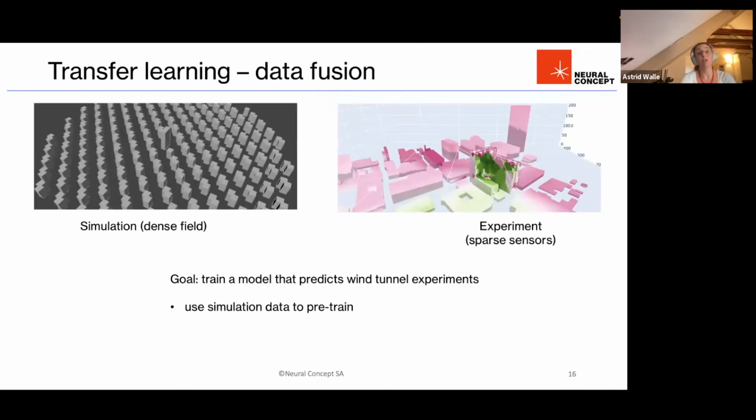Also, as I said, another thing that is nice here is that you're able to do data fusion, so you can combine data which comes from simulation with really heterogeneous data sources. You can combine simulation data with experimental results and train a model on both of them. Then you can also apply weights to them. So for example, if we think about CFD again and training a model which would be able to make the predictions, so that you don't need to run the CFD simulations for your next design program, then you can train it on a RANS simulation, but also on higher fidelity LES simulations.